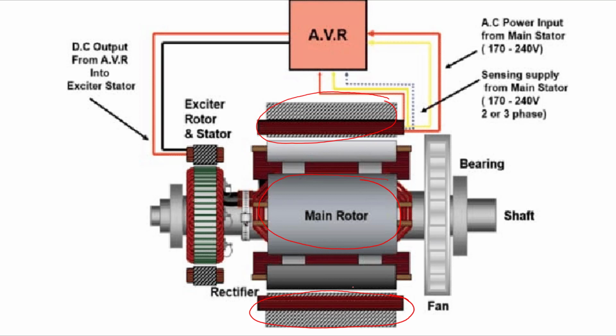But if you go to the power plant, you will find very huge synchronous generators, very, very big in size. They start from 500 megawatt to 1000 megawatt, and the voltage level it produces is around 10 kV or 11 kV, the terminal voltage of the generator. So we cannot collect such high voltage at the rotor circuit, because when the rotor rotates, if we try to collect it using the slip ring, the high voltage is quite difficult and it produces spark. So it is very, very difficult.